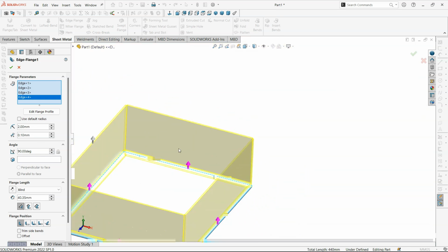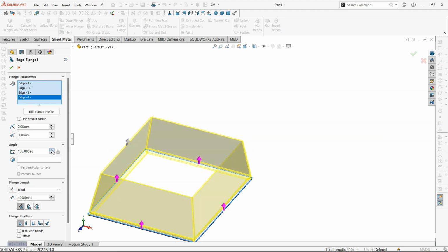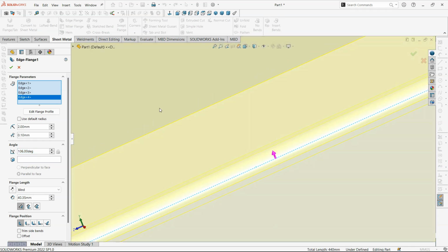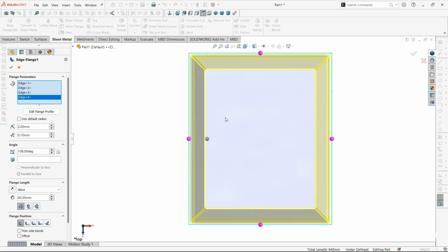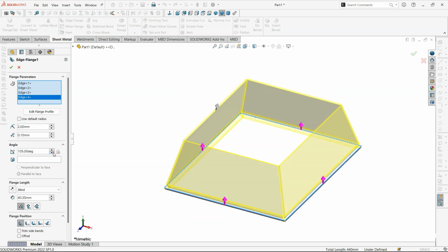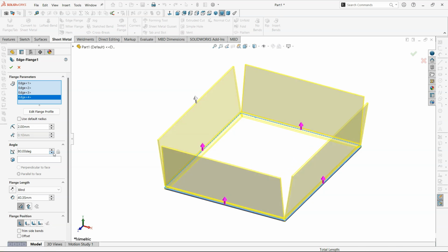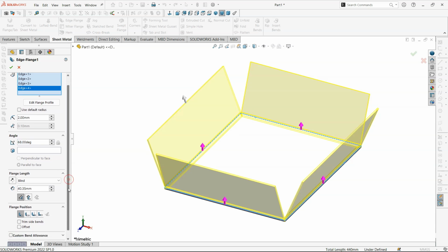And the angle here shows that if you want this sheet to be inward or outward, then you see if I increase the angle, everything is now going inward like a draft. So by keeping the distance between them 0.1. Again, if I go backward, you see here now it is opening. So you see the distance between has been increased, and now we cannot change the gap between them, because if we go outward the distance obviously increases between them.